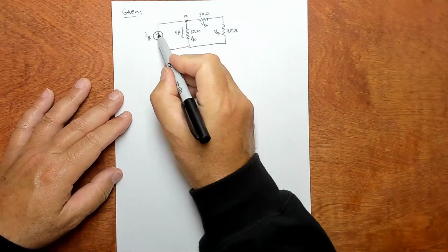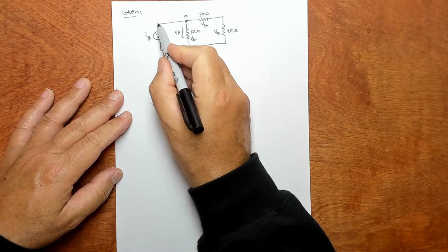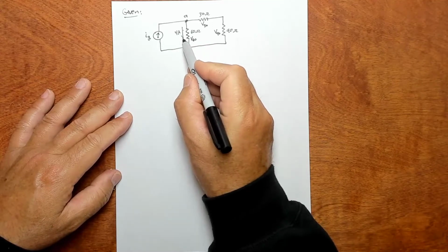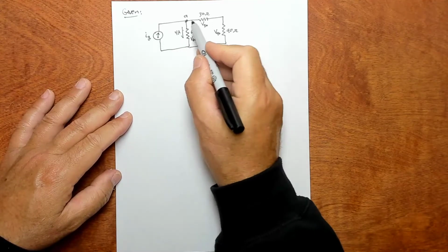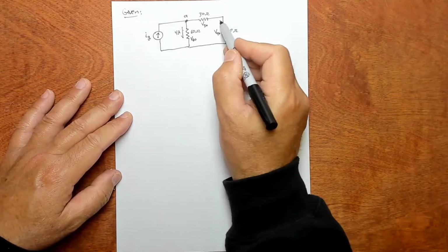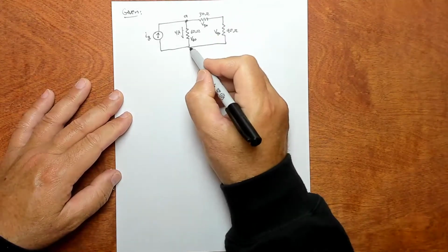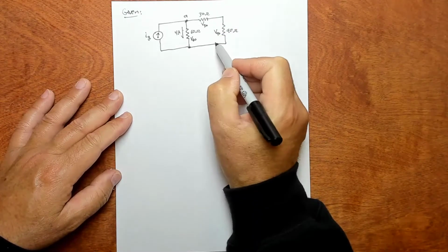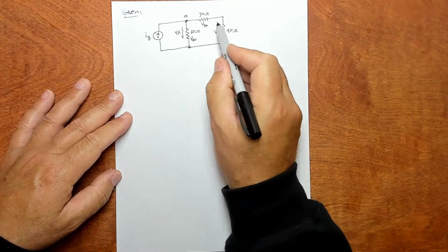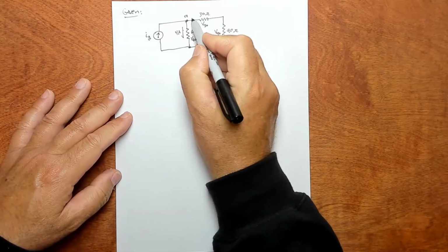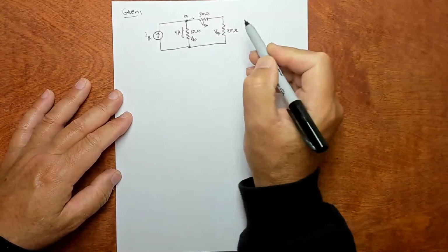All right, so we've got this current I sub G, which is going to come up in here and go this way, right? So some is going to split and go down this way. 4 amps of that is going to go this way. The rest of it's going to go this way. That's just what's going to happen. It's not going to come back. How to explain that? Well, just take that for now. That should sort of make sense to you, and it will make more sense when you get used to seeing more of these circuits. But basically, the current's going to go this way.